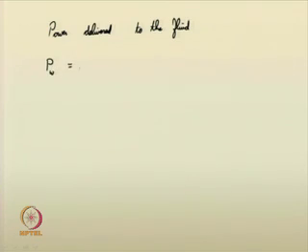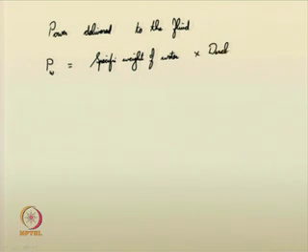So, Pw is nothing but the product of the specific weight of water or any fluid, the discharge, we have suggested that this is for a certain discharge, into the net change in head.